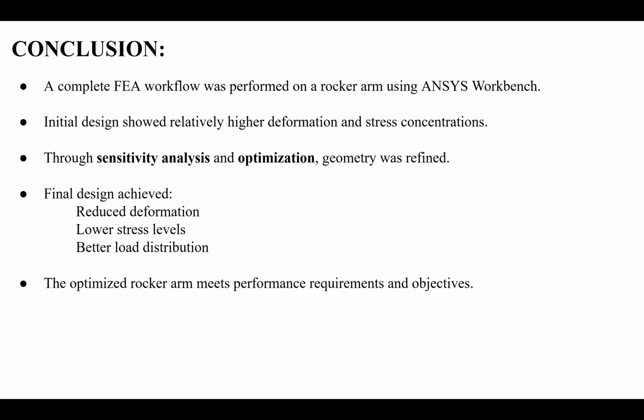So this project successfully demonstrates the entire workflow of finite element analysis applied to a mechanical suspension component. First, we performed geometry evaluation and meshing, ensuring a high quality quadratic tetrahedral mesh was used. Next, we analyzed the rocker under realistic push rod and damper loading conditions, with a combination of bearing load, symmetry constraints, and refined local elements. And we also observed higher deformation and stress in the initial condition.